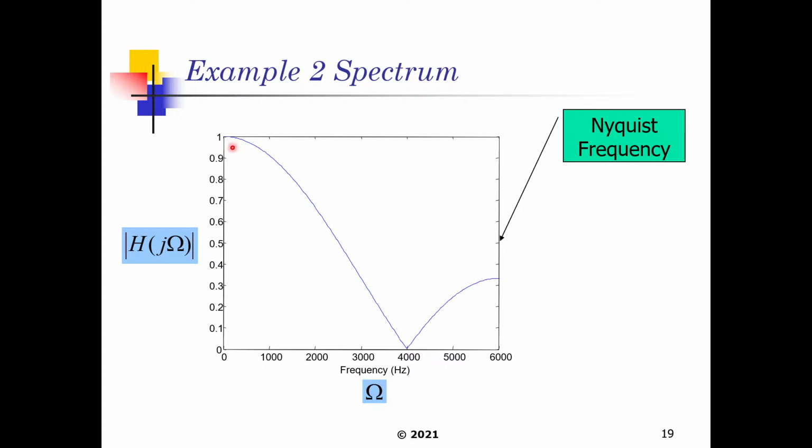And when we sketch our filter response, this is actually what it looks like. Remember, the Nyquist frequency is half that of our sampling frequency. So we see here that for our filter response, the symmetric part is going to be around 6,000 hertz accordingly.